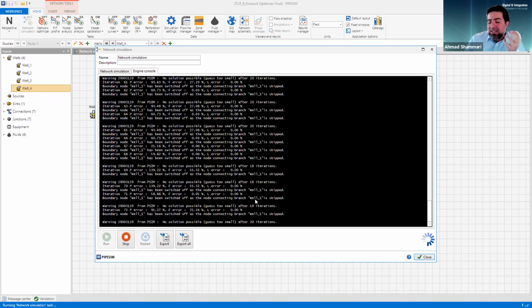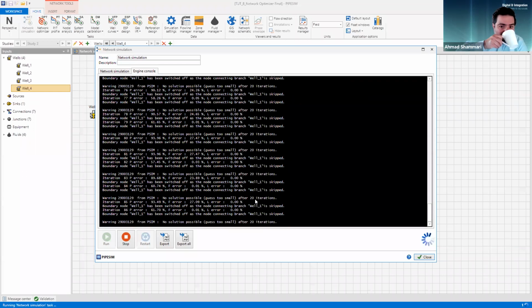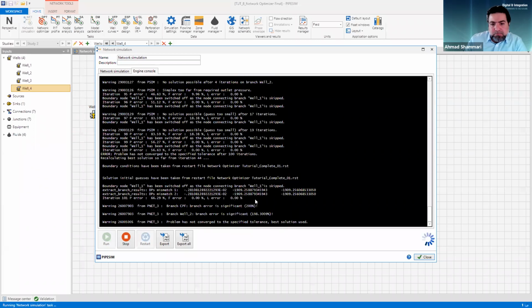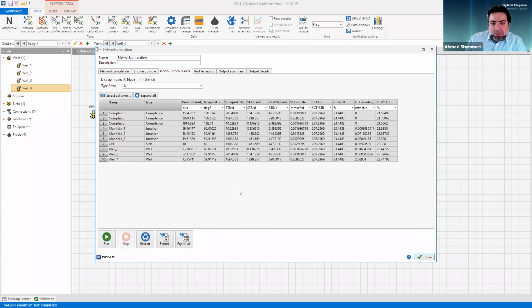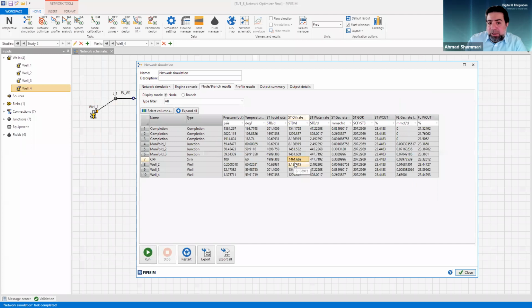So as you can see here, the gas lift is actually important for the wells to flow. So now when I reduced the sink pressure, then I start to gain some production. Okay, but I had to reduce the sink pressure. Now let's assume, if I now open the gas lift, what will happen to my production? Right now it's 1461, right?